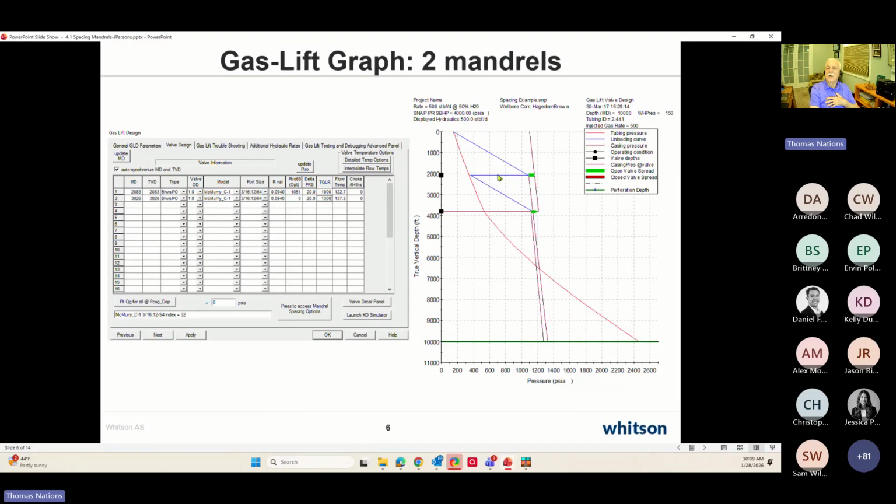If I had a gauge here at my gas lift mandrel depth, I would see this pressure moving slowly to the left as I increase my gas injection rate, till I get to here. When this pressure exists in the tubing, I have this gradient fluid below me in the casing. So this gradient line indicates what depth I would uncover the second gas lift valve.